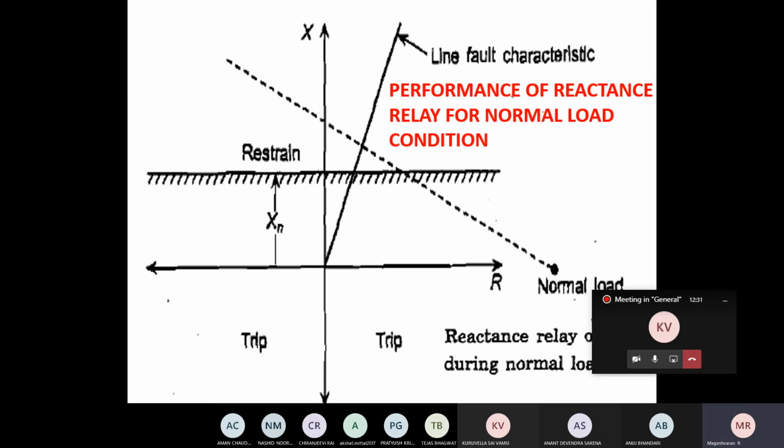Thereby, the chance of operation of the relay during the power swing is very high, which is not good, because most stable power swings come to a new equilibrium state and everything will be stable. But if the relay sees this as an abnormal operating condition and operates, it will land up in instability of the whole power system. This is what we discussed in the simple impedance relay.